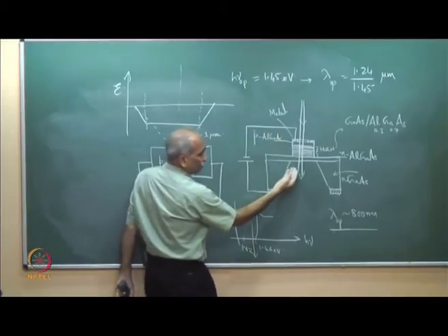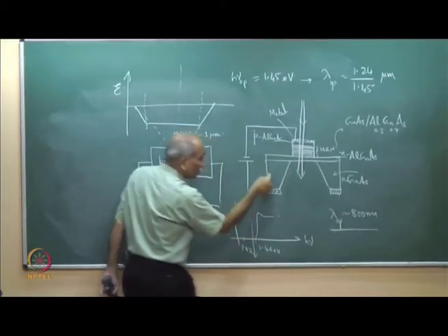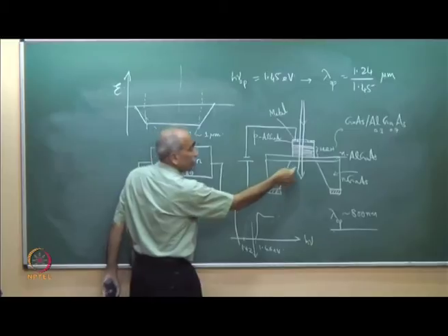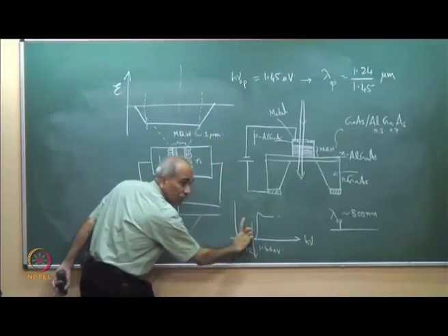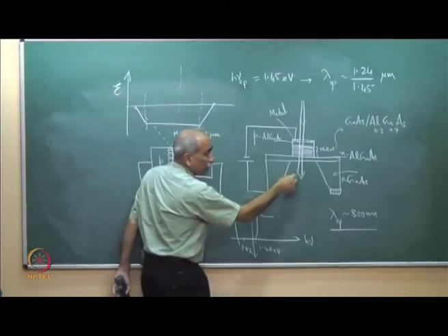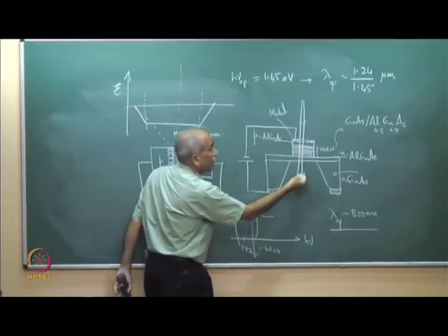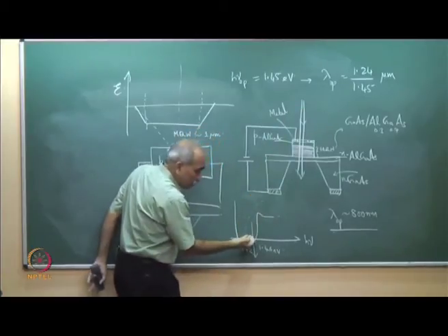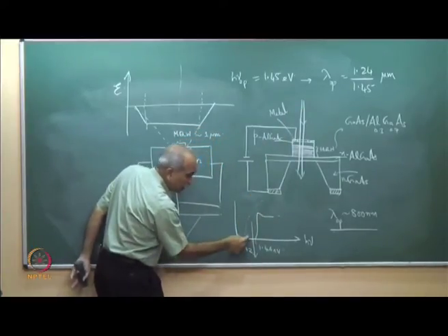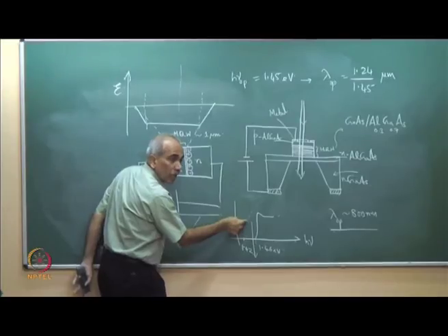Please note that we have etched this so that the gallium arsenide does not reabsorb the light. When this peak is shifted here, gallium arsenide could absorb the light. Light is coming at 800 nanometer, so gallium arsenide would absorb it. 800 nanometer is somewhere here, so the absorption coefficient is large.